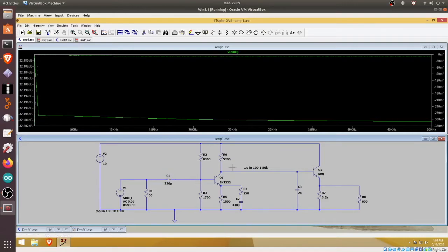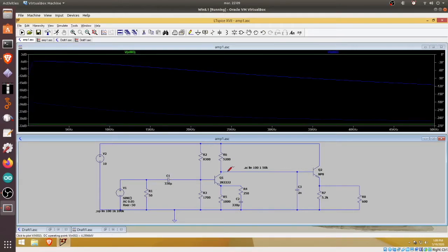This is the input. After the first stage of amplification, we get a much higher signal, amplified by a lot, almost, how much is that? Almost 40 dB. And this is because here I tweaked around with the resistors. So the trick to increase the gain is to have another resistor in parallel with the other one, with a capacitor. I'm not going to discuss why this is the reason, but if you study the common emitter, common collector amplifier configuration, you will discover why this is the case.